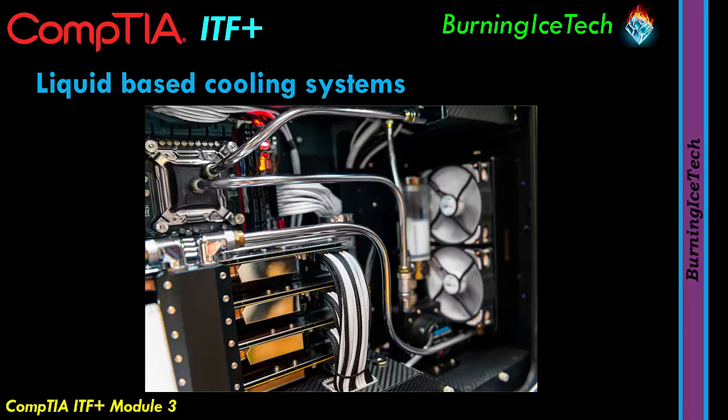But doing so, the engine obviously generates a lot of heat. Now, in case you guys didn't know, your engine actually has water in it, which gets pumped through the engine with the water pump. It pumps in cool water into the engine, and that cool water will in turn absorb the heat from the engine, and then the water pump pumps the hot water out of the engine to the front of the car to the radiator where it gets cooled down again, and then that cooled down water gets pumped back into the engine.